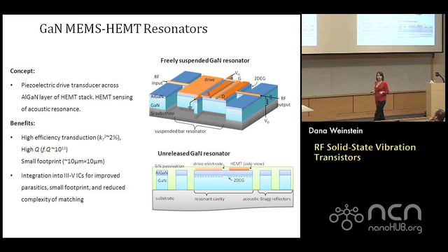Okay, what do these structures look like? Well, again, we're leveraging the benefits of transistor sensing of acoustic vibrations. So before, I had a capacitive drive and a FET sensing on this resonant cavity, right? So now, gallium nitride is piezoelectric. I want to leverage that, right? So instead of capacitive drive, I can generate fields in this aluminum gallium nitride and gallium nitride stack, and piezoelectrically excite vibrations in the structure.